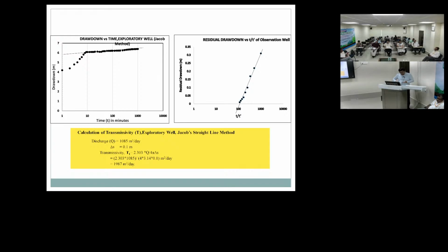That is because of the pressure, because it is under constant pressure. Suppose I have given you the example of puncturing a balloon. Overburden is, ultimately, a stack of earth material or valley fill deposit or anything. So what is an aquifer? An aquifer is where it is porous, permeable, and it has to hold water. So when you drill a hole, we have to cross the overburden. After that, once you touch the water surface, suppose the aquifer surface, it will rise above, it will come above its own aquifer area because of the overburden pressure.